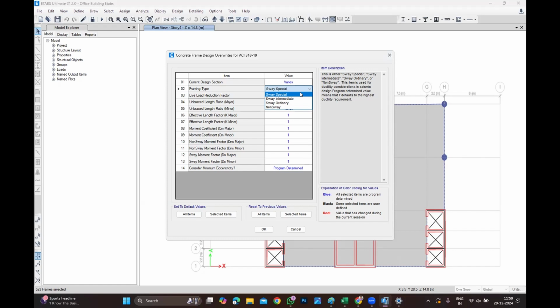If you don't know, consider site class B. But if it is mentioned in the geotechnical report, consider whatever it is. I'm talking about only Dubai, not anything outside the country.